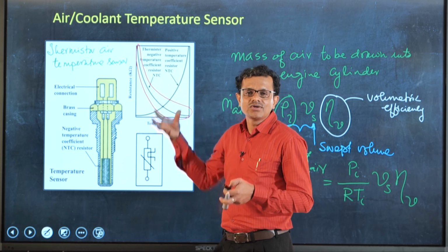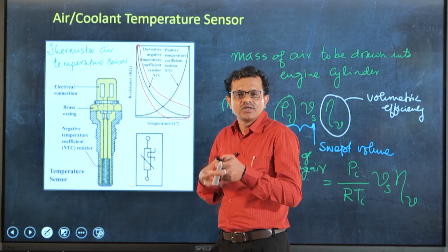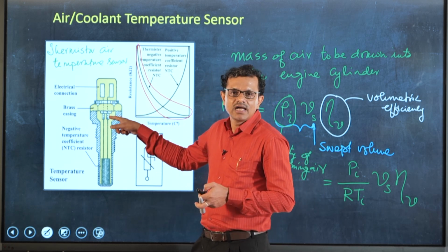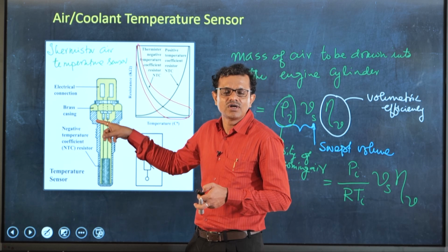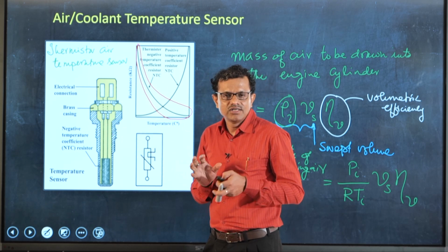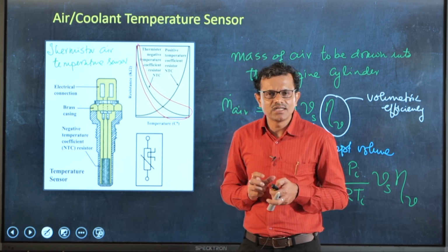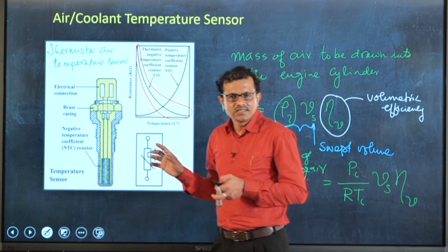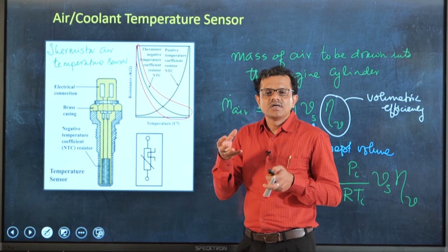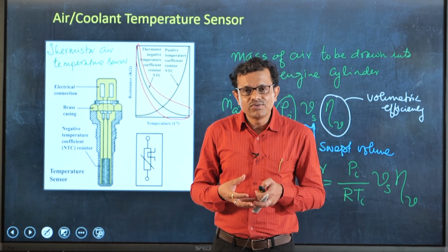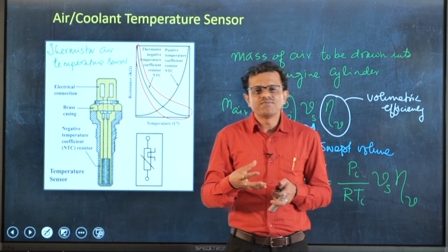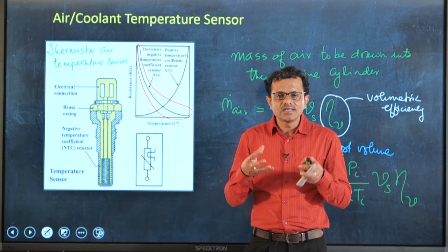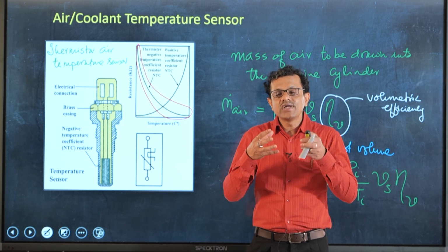Certainly the voltage at a higher temperature of the incoming air should not be the designed or accepted voltage from this particular sensor. So, a change in voltage from this sensor will be read by the microcontroller unit, which will give feedback to the electronic control unit, and then the electronic control unit will set up some correction so as to control the fuel injection time.